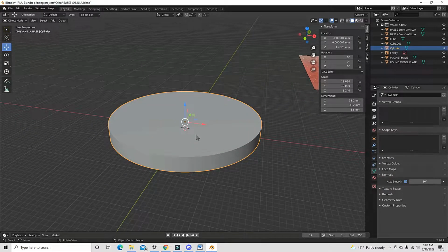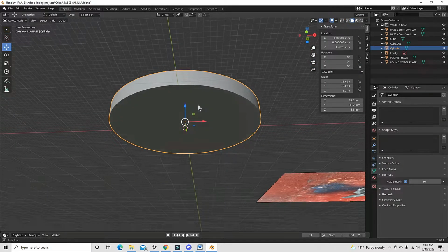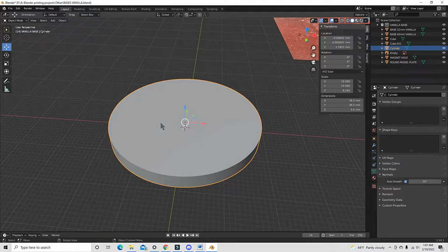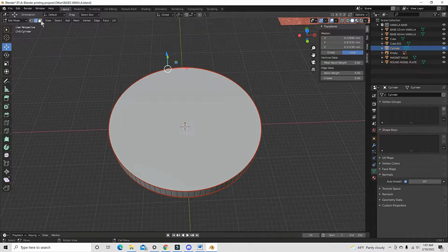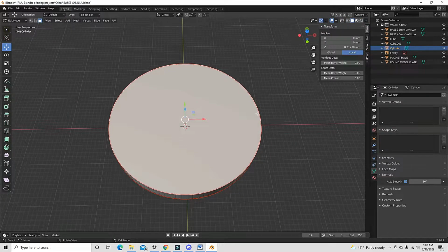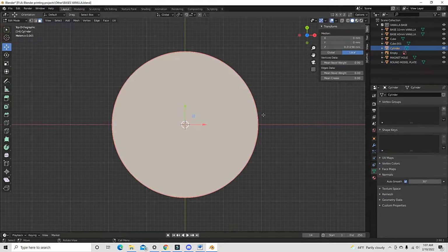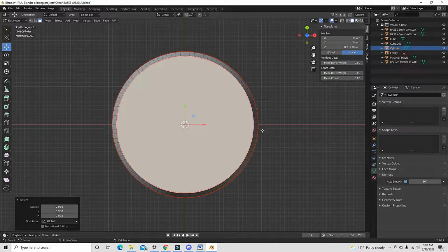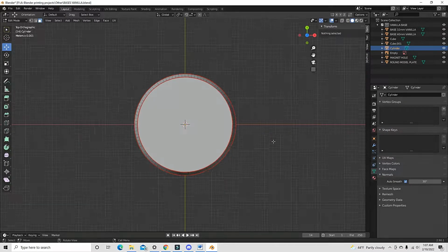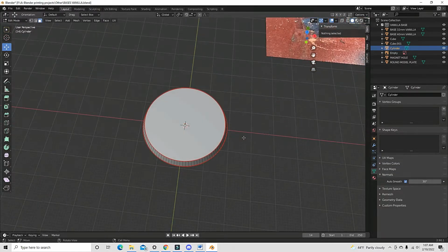So, one thing I've noticed is that the bottom of the bases and the top of the bases aren't the same size, essentially. So, I'm going to click on this, press tab, switch to edit mode, click on this to switch to faces, grab the face, and we're going to scale this down just a bit. Press 7 to look up top. The actual size we want to bring it down is by 2mm, which is a little difficult to grasp here. How much is 2mm? So we'll actually figure that out.